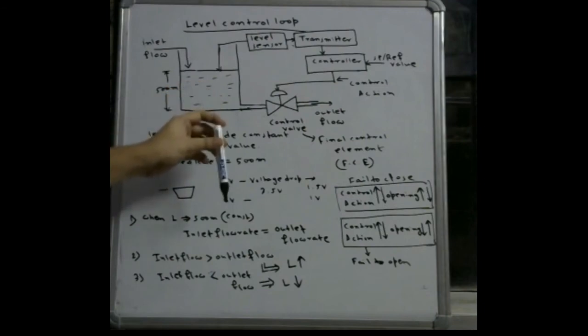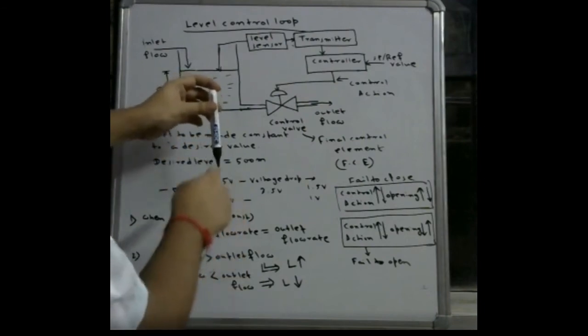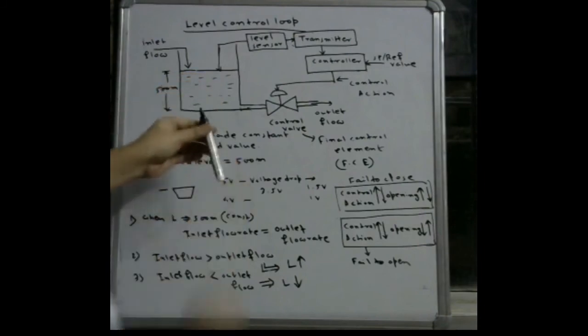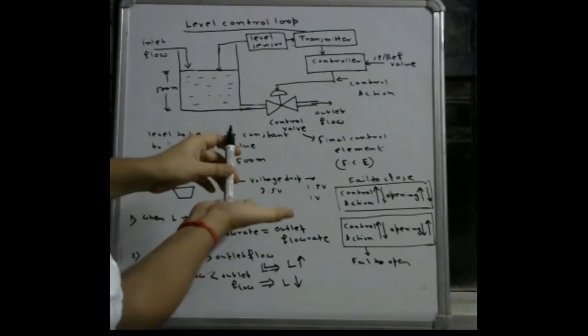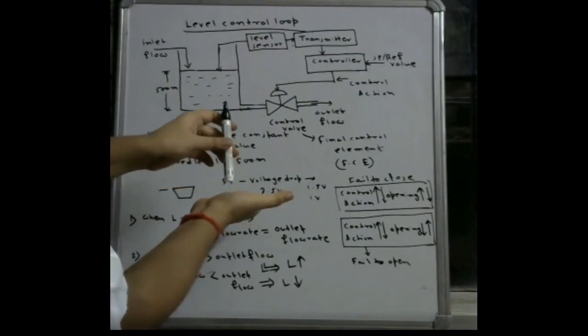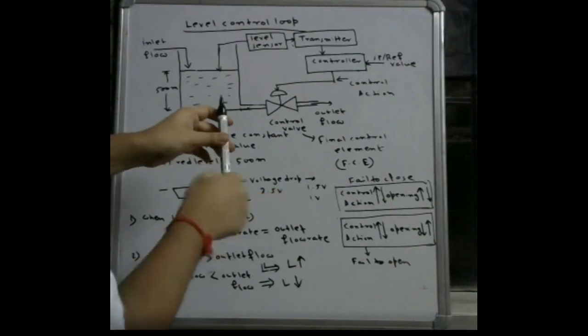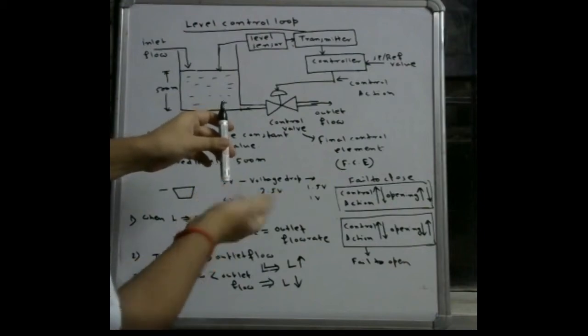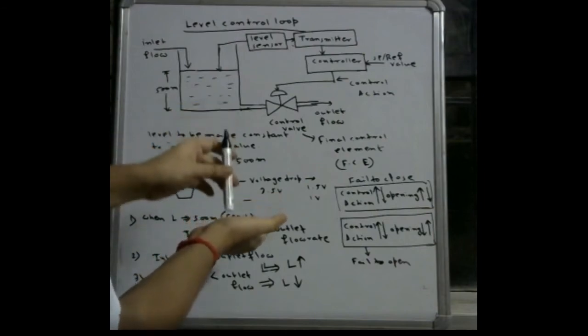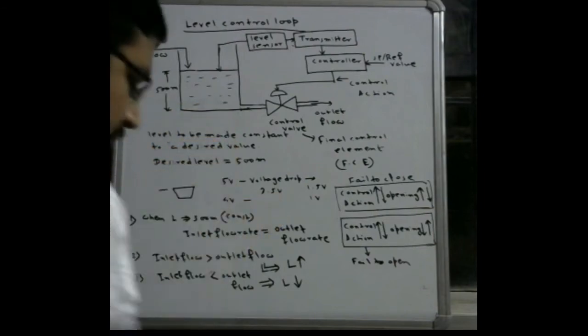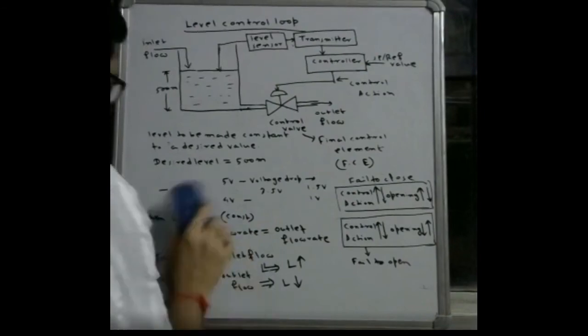So this plug actually moves up and down through the pipe, through the opening of the control valve. If the plug is lifted upwards, then the opening is increased like this. Suppose this one is completely blocked now. As this one goes upward, then it will be open. The opening is open. And if this one goes downwards, then the opening is decreased.